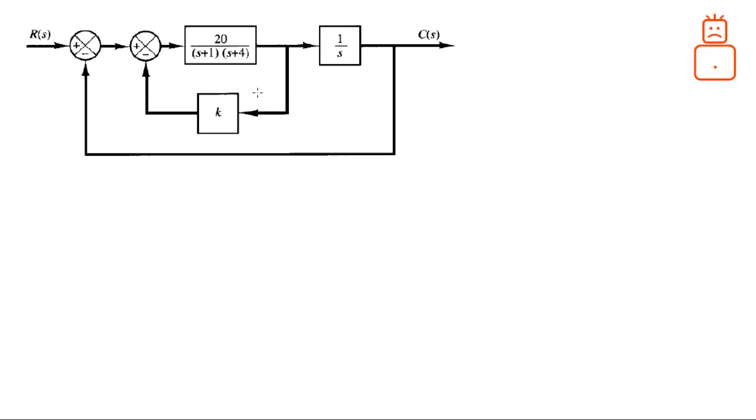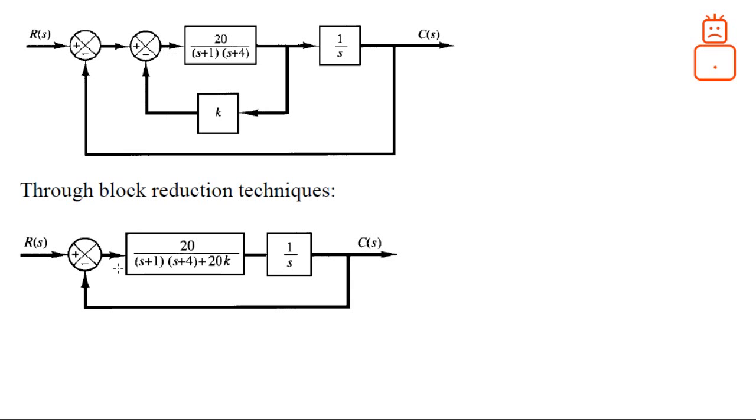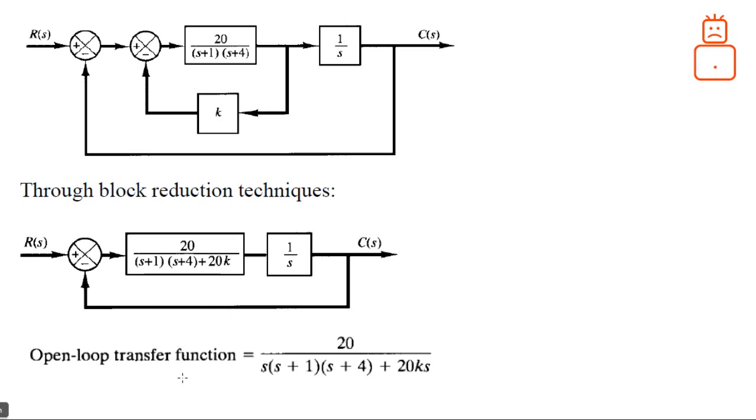function of the system. We can achieve that by using block diagram reduction, where we're going to treat this inner loop as a feedback system and use a feedback equation for that. We're going to arrive at this formula here. This function here is in the standard format, so we can find the open loop transfer function. Since it's not being drawn for variation in the controller, it will be drawn for the variation in the k.